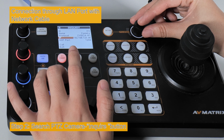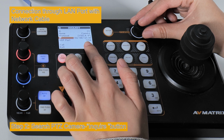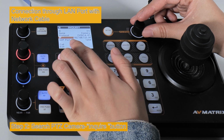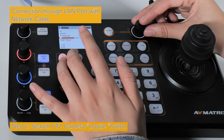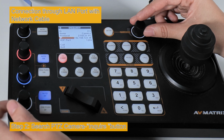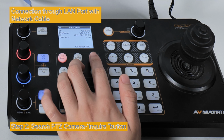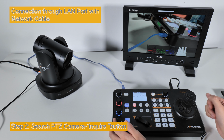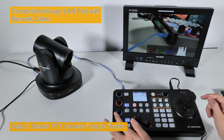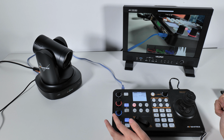And the IP address should be set as the PTZ camera's IP address, which, as we know, is 192.168.123.38. And then press call. This time we can also control it successfully. And this is about the connection through LAN port with network cable.